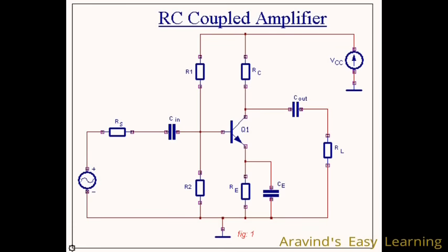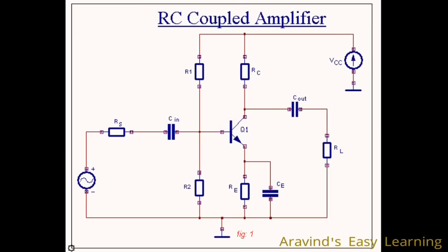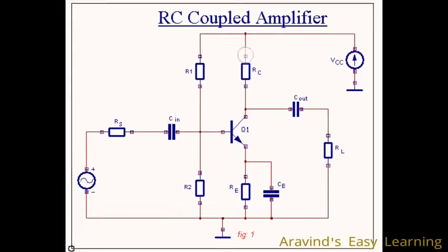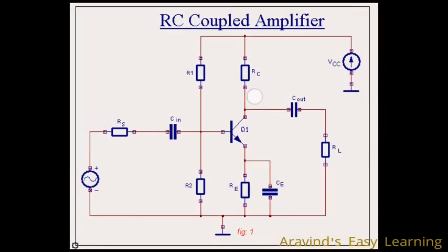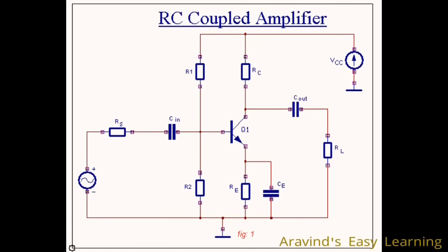Even though it may not look obvious, there's an inter-electrode capacitance that can be formed in 3 junctions like this. Here there can be an inter-electrode capacitance, here also, here also. But we didn't speak about this inter-electrode capacitance before. But why am I speaking of it now? See, the inter-electrode capacitance is not a big factor to be considered. It is almost always neglected. But at high frequencies, this needs to be considered.